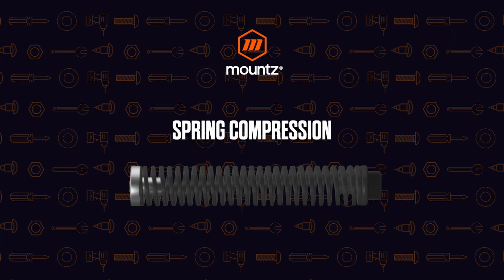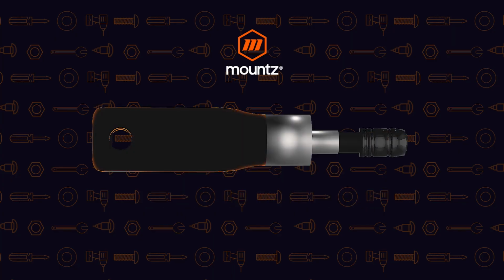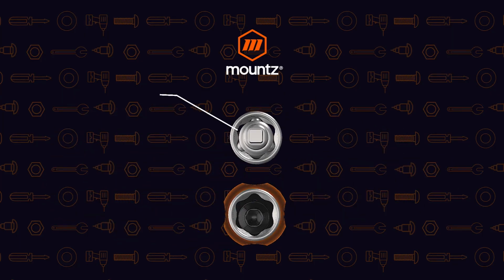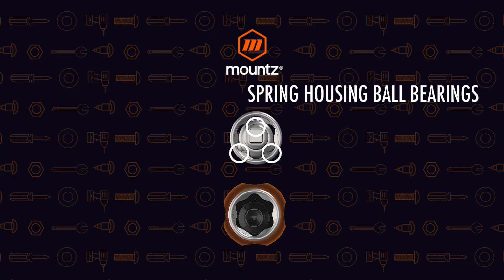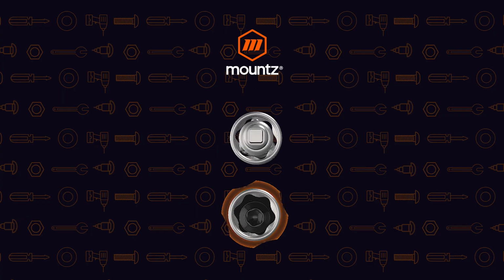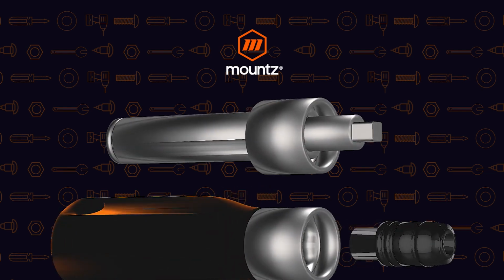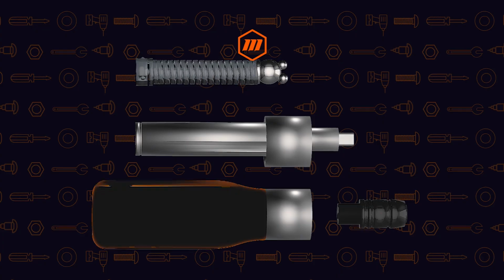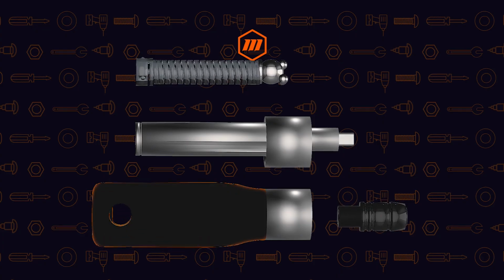Now, this is accomplished by the use of a cam mechanism within the internal body of the screwdriver. So we have three ball bearings that sit inside a cam housing. And as we rotate the tool, those ball bearings will push in on a single ball bearing, which compresses the spring.